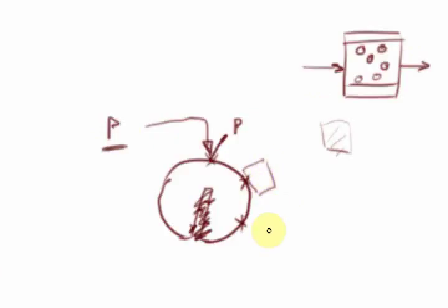If we knew it was carbon that was depositing onto particles, or if there was some other kind of deposition going on, then we could look at the chemical involved and look at some way of washing it out. If it's carbon, for instance, what's often done is periodic incineration of the particles so that you just burn off that carbon. If you know that sintering can cause your particles to break down, then what you could simply do is use some other, better support for your reaction conditions.